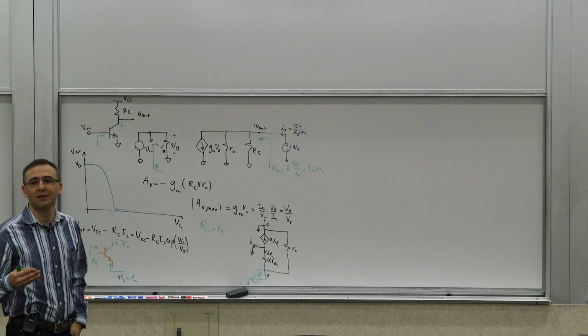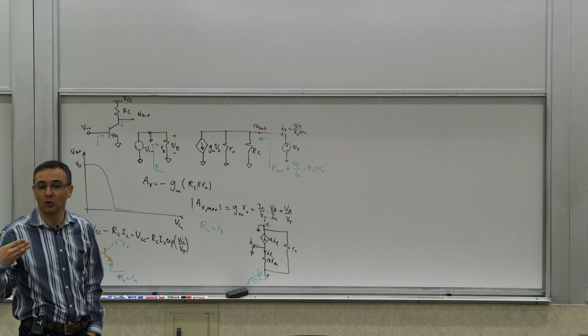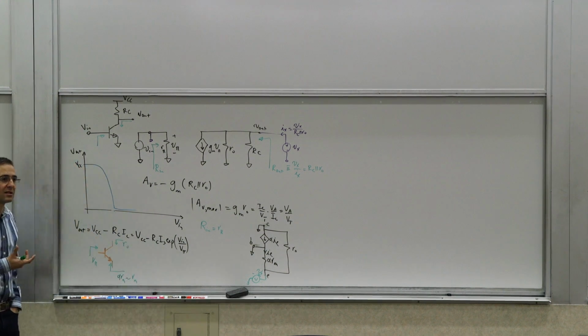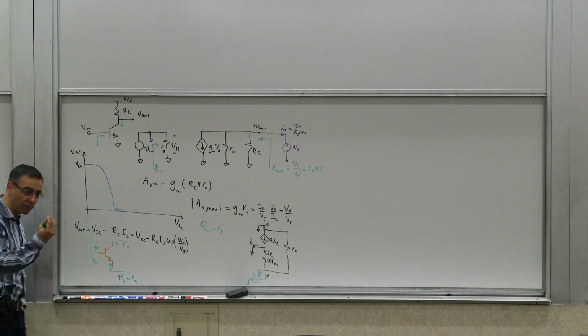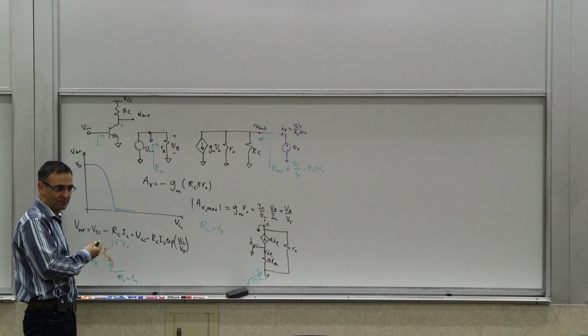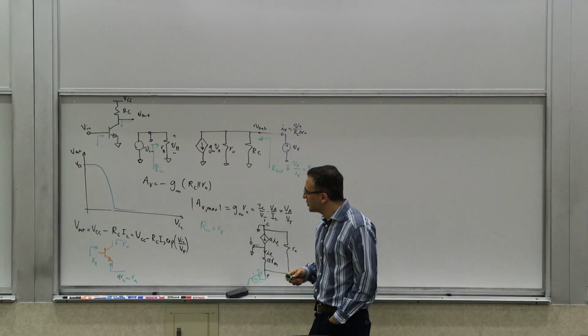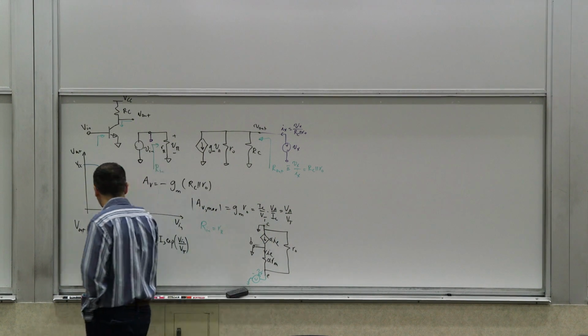And this is important when you design circuits because there are places where you need low impedance and there are places where you need high impedances. And that would affect the way you use the transistor. The topology of the design is really dictated by these impedance levels, primarily. So that mindset should be on the back of our head as we go forward.